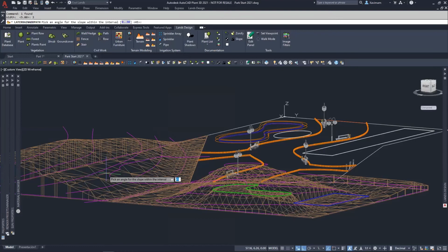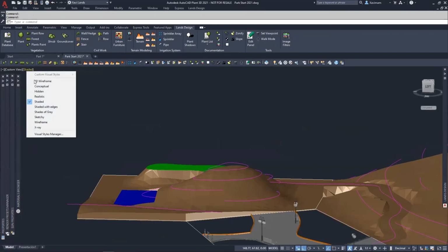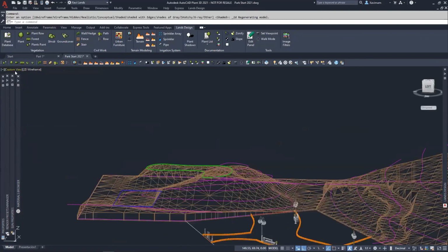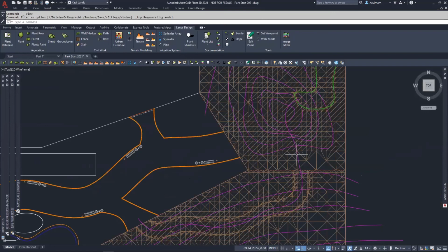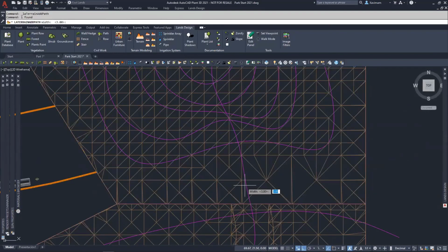And then I'm going to make a 45 degree angle as well, or I can make it higher, for example, I make 75. And I select the curve. And the terrain, as you can see, is being modified to create this shape. And of course, I have to do the same on the other side. I'm going to repeat it in wireframe, top view, whatever you can move. In this case, I'm going to select the terrain, add path, 3 meters, or 10 feet, 75 degrees, curve.